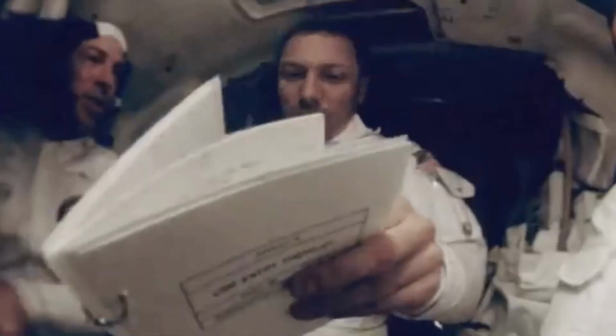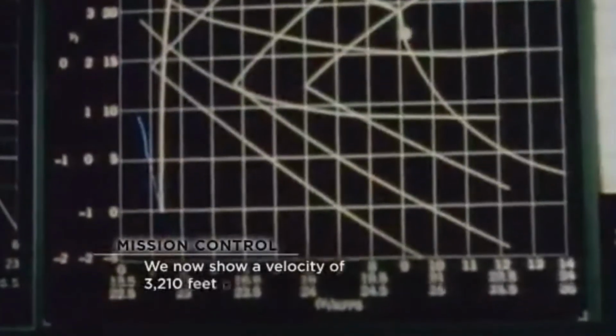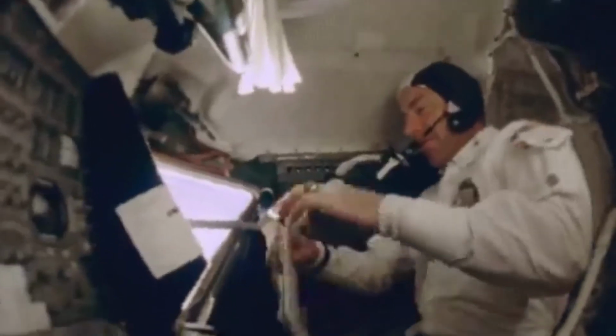In the astronauts' heroic attempt to save their spacecraft, they abandoned their moon landing and powered down the CM to save power, which they would need for re-entry into the Earth's atmosphere. Since the CM was powered down, that meant that the AGC was powered down as well, which meant no navigation system. They had to rely instead on the LM's navigation system to get them back to Earth. But because the LM's primary guide and navigation system, the PGNS, would have used too much power, which was now limited, they instead used the backup computer, the LM's abort guidance system, AGS, to help navigate back to Earth.